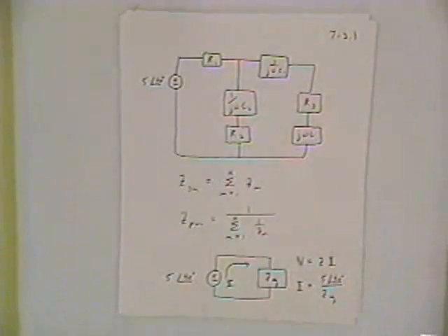Now you have a number of examples of this in your review material, and this is the kind of thing that you need to practice and practice and practice, just to make sure that you don't make careless mistakes like 1 over J equals minus J is the correct way to do it. If you forget that and you mess up the minus sign, that's going to throw off all your calculations. So one thing I would recommend to you is go to the review materials and practice a lot of these AC phasor problems.